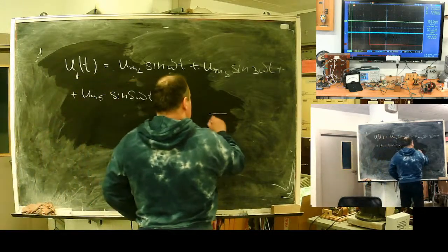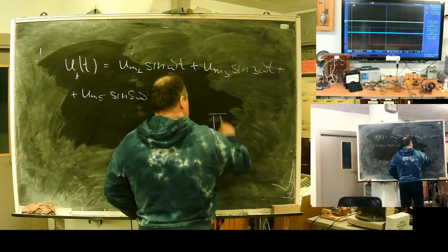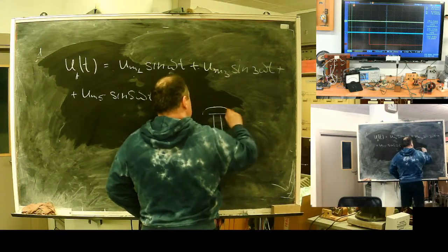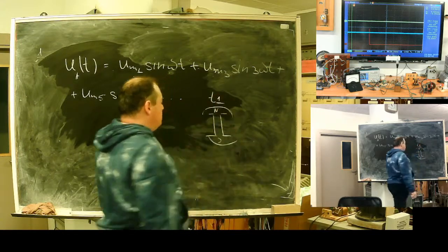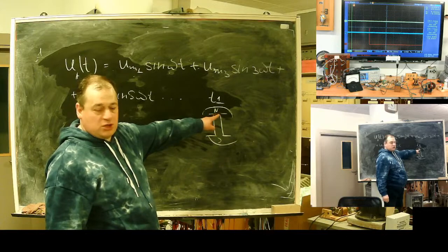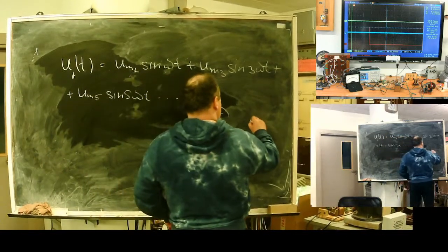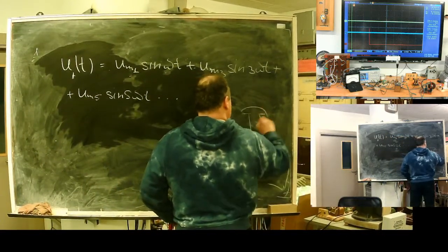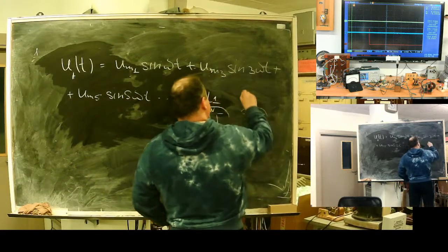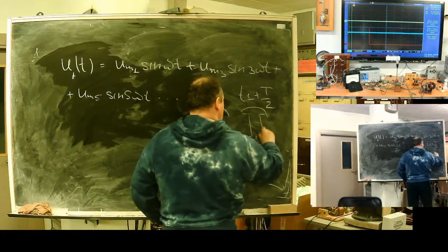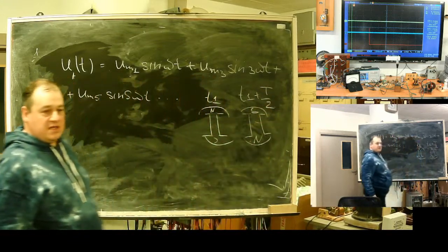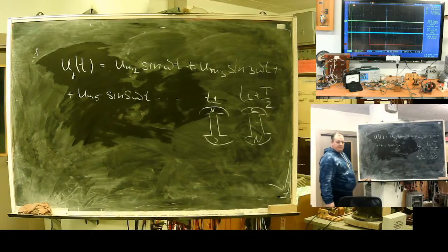Because, it's not an advertisement of Bosch. If at moment 1 you have this position of rotor, after half of period it will be opposite. And due to this symmetry, even harmonics disappear. You need diodes or thyristors or something active to get even harmonics in the voltage.